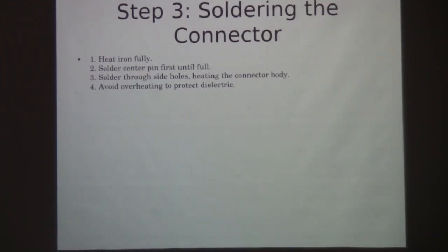So you want to make sure, and this is the hard part, that your iron is really hot. It takes a lot of heat to solder these things. The center pin is going to get soldered first, and you want to fill that whole center pin up with solder until the hole fills. That way you know you got a good connection.